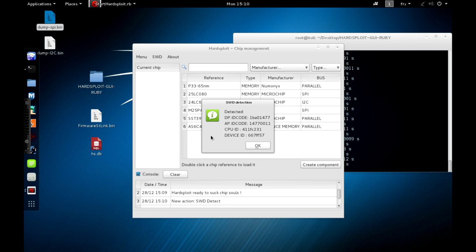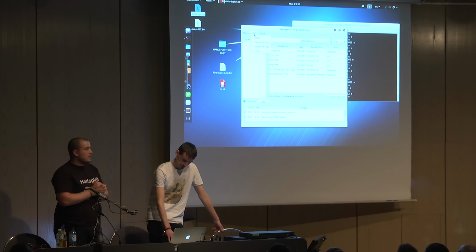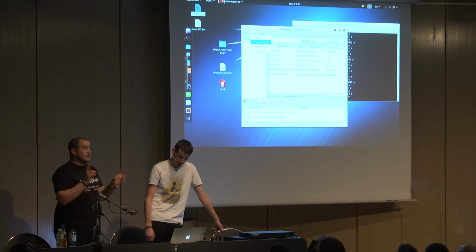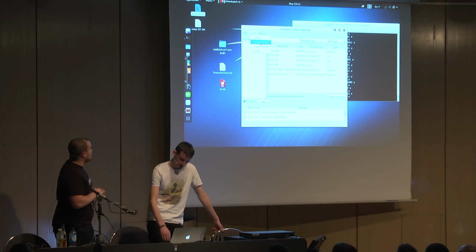If you read the data sheet, for this chip you just need to use this address with this size. But the size, you can read the size of the flash directly inside the microcontroller. So it's an automatic tool because the SWD protocol sends good information to read all the content of the flash. So it's perfect. You plug, use detect to be sure all the wiring is done, and after just import or export, like dump. It's easy. Let's try the dump, for example.